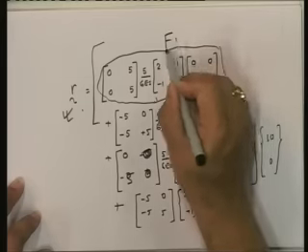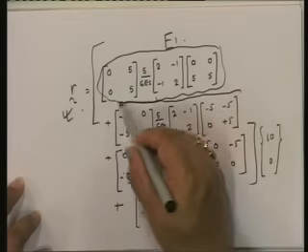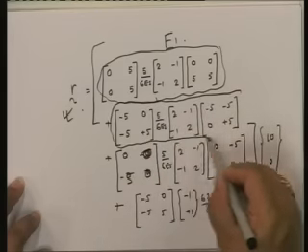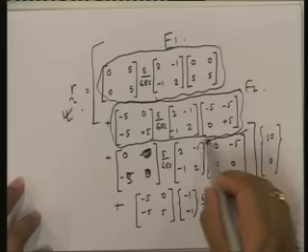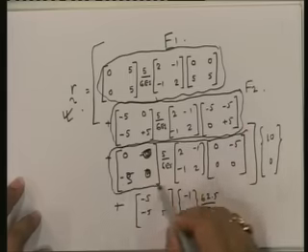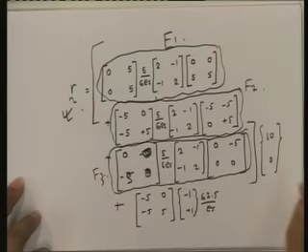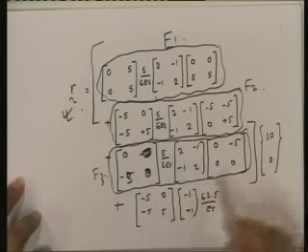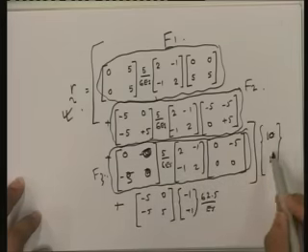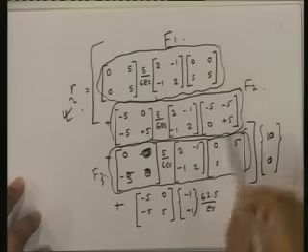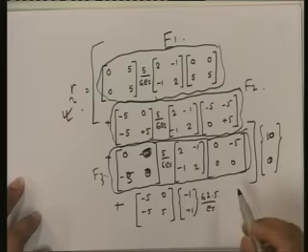is the contribution to the flexibility matrix of member 1. This is F2, this is F3. So if I add F1, F2, F3, that gives me the complete flexibility matrix multiplied by 10 into 0. So this gives me the structure flexibility matrix for this particular structure.